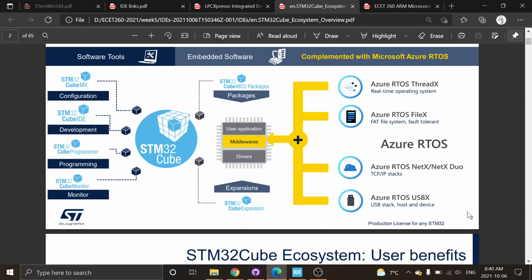If you go and use Keil right now, the free version is limited to 32K. And then same usually with IAR and a number of the other different development packages. One of them, I think IAR might actually be limited to 12K of code. And so when you start bringing in different libraries, like when we do the graphic libraries and stuff in a few weeks, you're going to find that we're easily 100K of code.